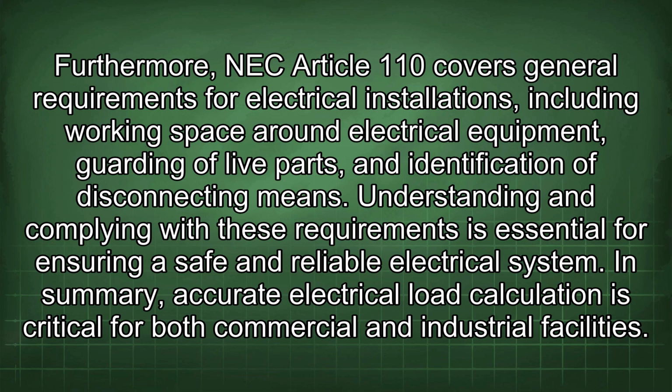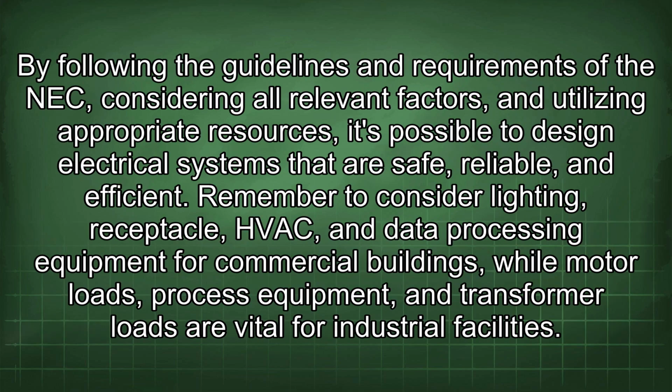In summary, accurate electrical load calculation is critical for both commercial and industrial facilities. By following the guidelines and requirements of the NEC, considering all relevant factors, and utilizing appropriate resources, it's possible to design electrical systems that are safe, reliable, and efficient. Remember to consider lighting, receptacle, HVAC, and data processing equipment for commercial buildings, while motor loads, process equipment, and transformer loads are vital for industrial facilities.